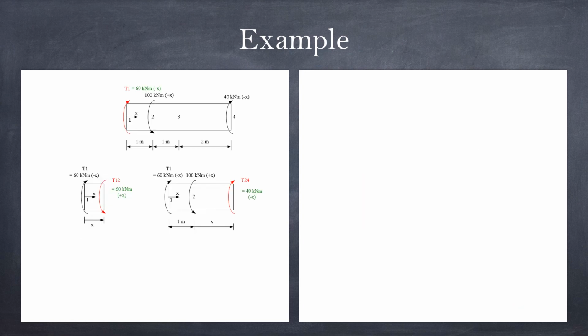Okay, for the same free body diagrams, we can calculate phi between 1 and 2 as follows. And I have to emphasize this is between 1 and 2. It's not absolute yet, it's just between 1 and 2. And we also can calculate between 2 and 4. Notice the way the phi goes and the torsion goes. It always goes the same way when you calculate relative ones. This one here is relative. The first one on the left-hand side is between 1 and 2, the difference between 2 and 1, and the last one is the difference of 4 compared to 2. But it's not an absolute.